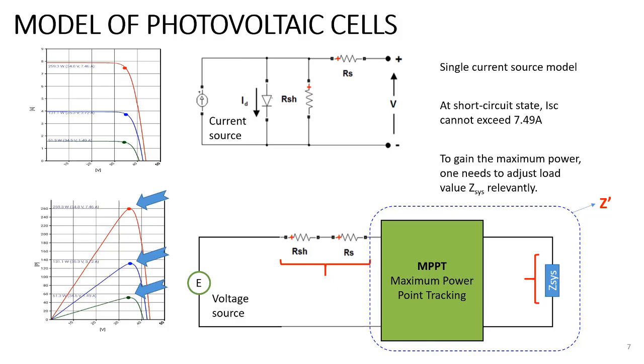Right. Thus, with the support of the maximum power point tracking system, we could keep all the panels working at their best output power condition at these points. Meanwhile, if the PV panels are connected in series, they will share the same current value. This leads to the fact that the output power produced at each panel is not at its best efficiency, and the common current is significantly reduced.